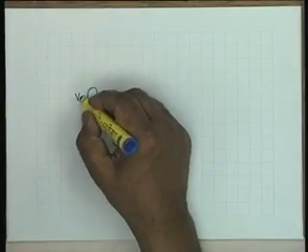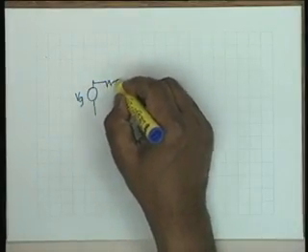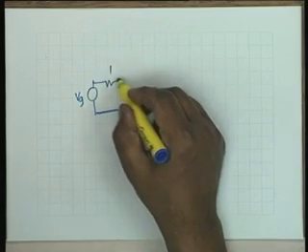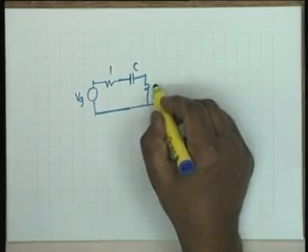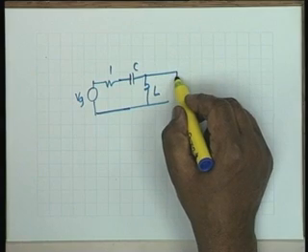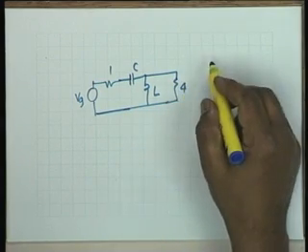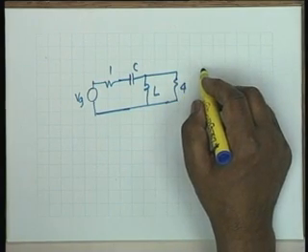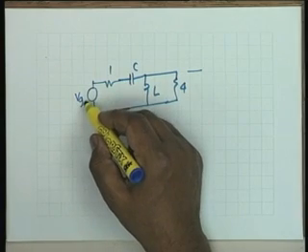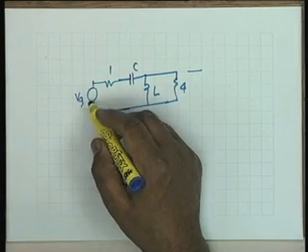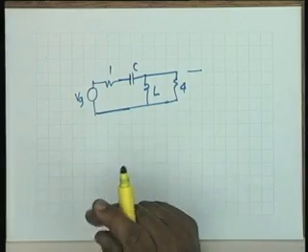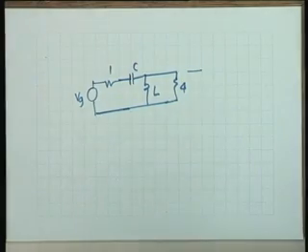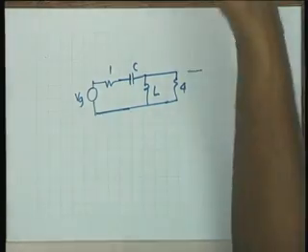Let's see what our Vg is, and then we have 1 ohm. Let's take this C and L. We are given V2 by Vg, not V2 by the voltage input at port 1. It doesn't matter. I have to calculate V2 by Vg. Can we directly guess that the network is LNC? Oh yes, of course. 2 transmission zeros at the origin. There is no other way. These are the only 2 ways.